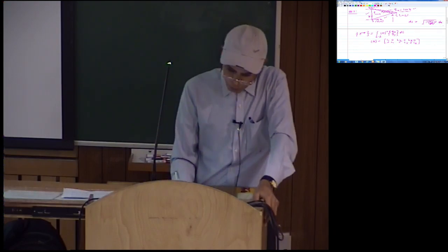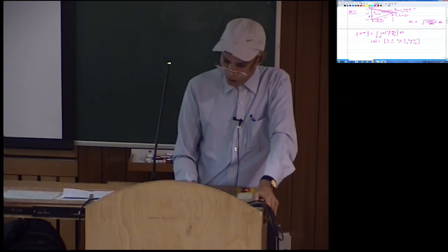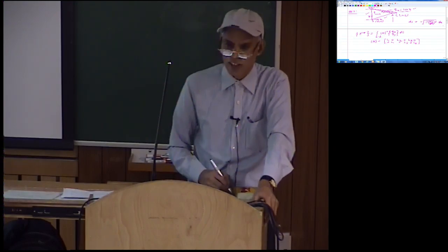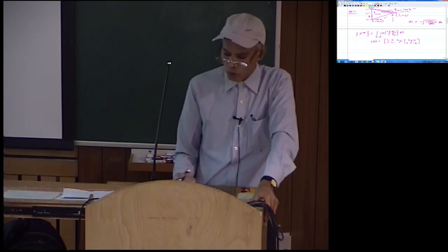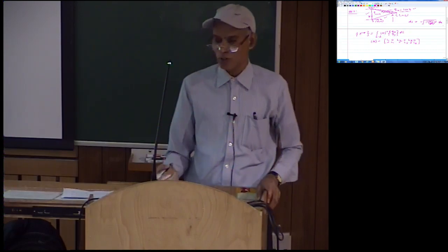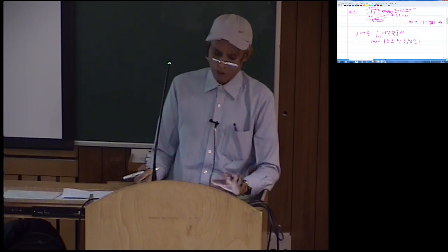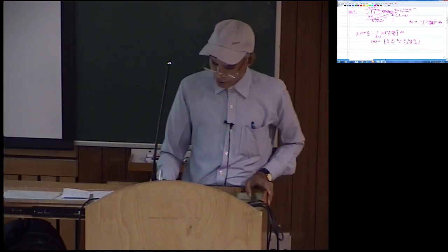But in this case, if you are going from 2 to 3, so x is decreasing, but s is a length, so it must be positive, so you put a minus sign here. If you are going from 3 to 2, then ds is equal to this into dx. That will take care of the sign in the load vector. Finally, it has to be basically a positive load vector.